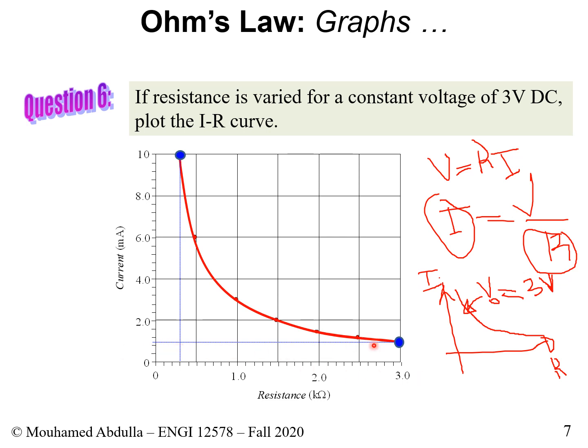And again, both of them should work with Ohm's law. So we could try it. Maybe I could just write it here. So this is 300 ohms. And this one here is 3 kilo ohm. And this point here is 10 milliamp. And this one here is 1 milliamp.